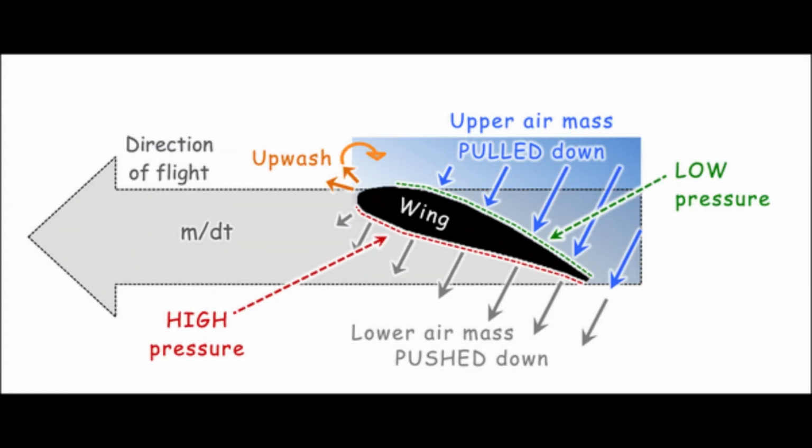In a wind tunnel or in flight, an airfoil is simply a streamlined object inserted into a moving stream of air. If the airfoil profile were in the shape of a teardrop, the speed and the pressure changes of the air passing over the top and bottom would be the same on both sides. But if the teardrop-shaped airfoil were cut in half lengthwise, a form resembling the basic airfoil wing section would result. If the airfoil were then inclined so the airflow strikes it at an angle, the air moving over the upper surface would be forced to move faster than the air moving along the bottom of the airfoil.